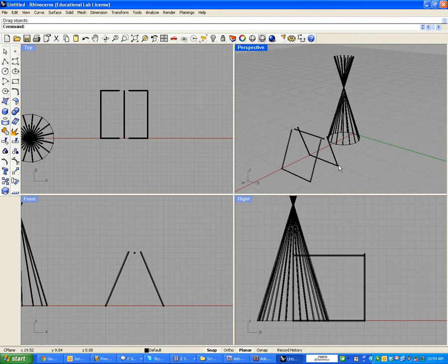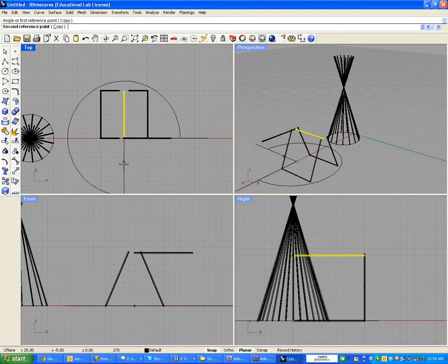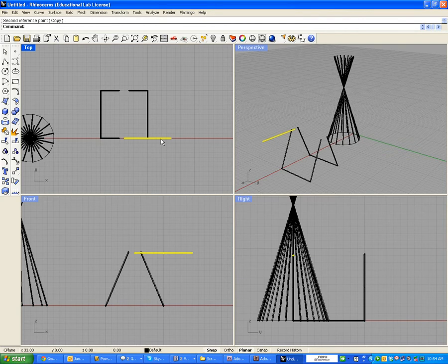What we need to do is that we have 2 other cylinders that we need to create on the base so it can hold. So this one that I have over here, I'm going to rotate it, and I'm going to make it horizontal. So I'm going to click on Rotate, and this time my center of rotation is going to be on the top view, and I'm going to put it completely horizontal. And of course, I need to copy and paste it and put it right there. I'm going to copy and paste it again. Okay, and I'm going to put it there.